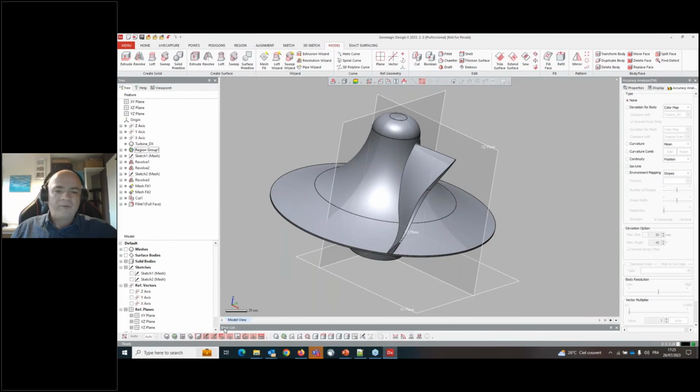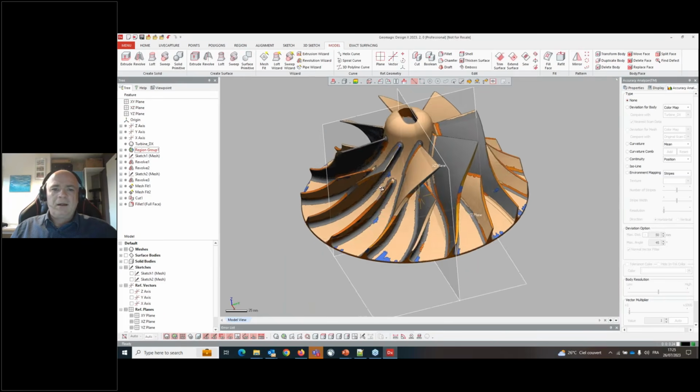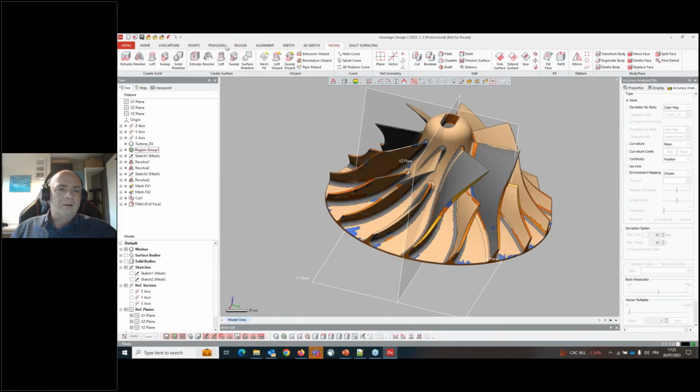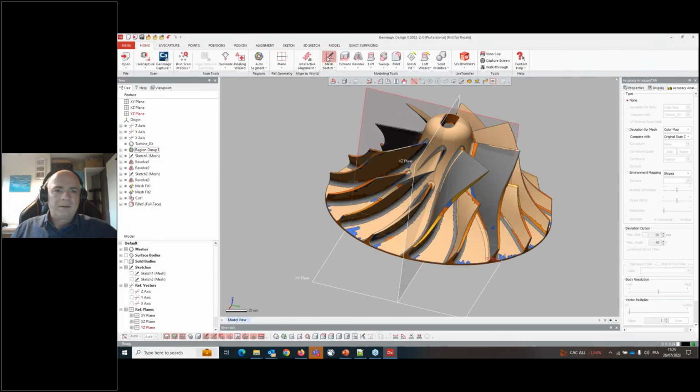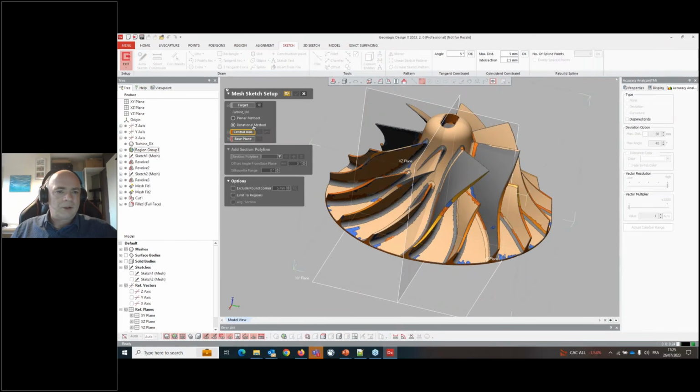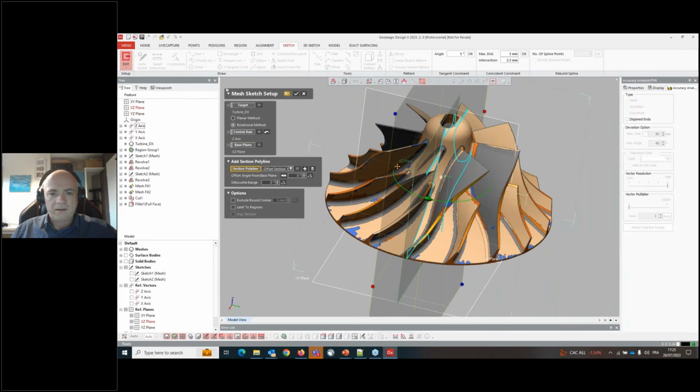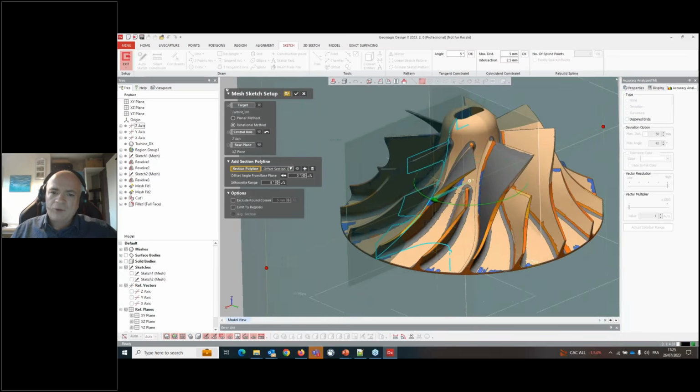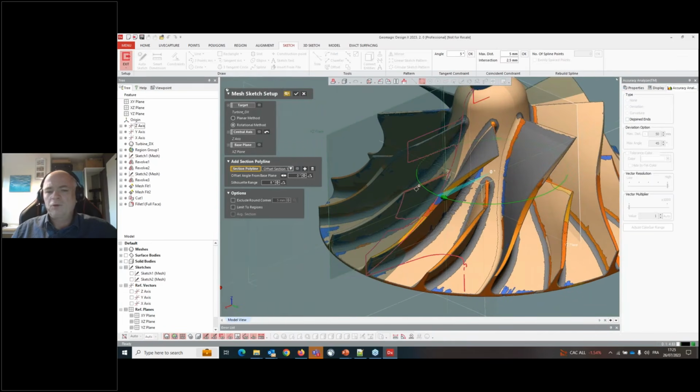So it's going to be roughly the same process. I will do again a mesh sketch. Again, rotational method, the axis still Z. The plane is going to be here. And I will again take a little thickness, but that time I would just need to have that line. So I don't really need to be very far. I just need to have that height and okay.